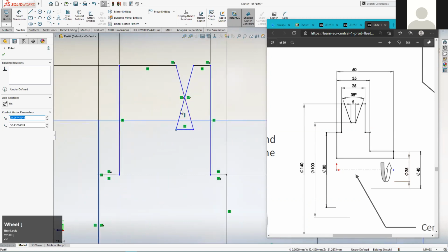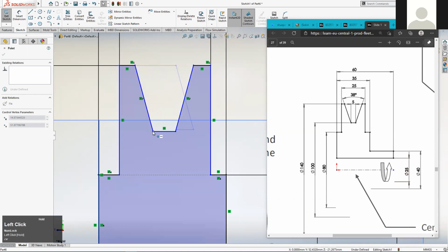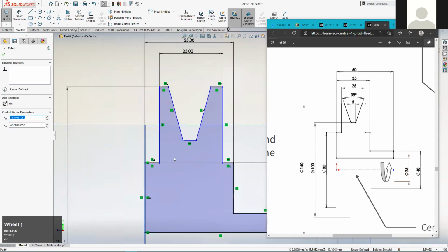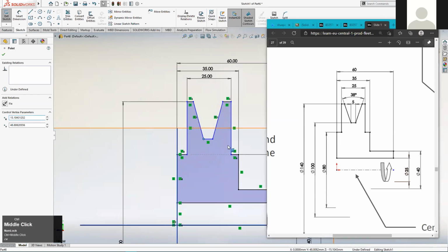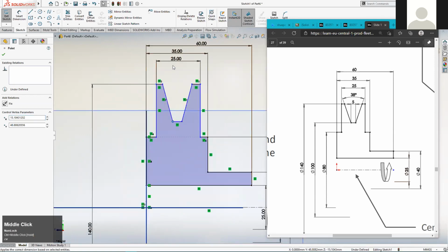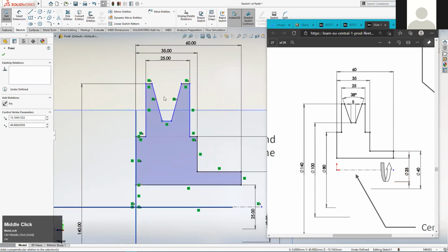We ended up having to trim away the ends of these lines to try and correct it. So that's why we're doing it today very tentatively and very slowly and methodically, going between creating bits of the sketch and then adding dimensions and then creating a little bit more and adding a dimension. It's just to avoid those sorts of pitfalls.